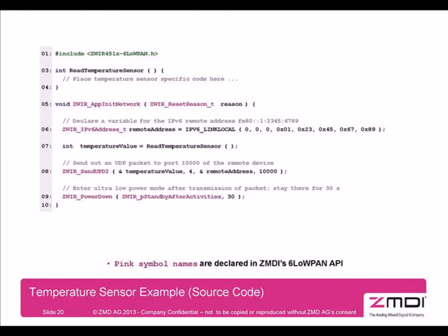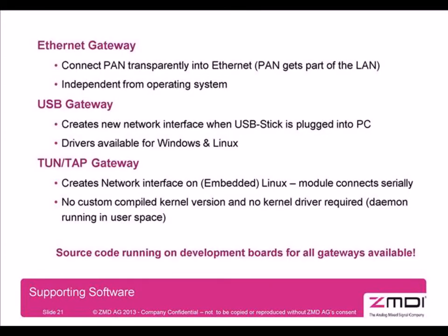For this USB gateway, we have drivers for Windows and Linux. We are using the default drivers for this. And of course, we have a TUN/TAP gateway. This creates a virtual network interface on a Linux PC, and in this scenario, the module or the gateway is attached to and communicates via a serial interface with the PC. And as I said before, the source code is running on the development board, and all the source code is given for free.